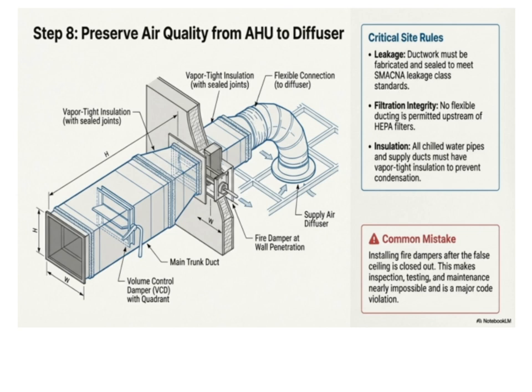They must always be accessible for inspection and maintenance, so in case of a fire, they can be quickly operated to contain the spread of smoke and flames. Finally, vapor leaks are a serious concern because they can cause condensation within the ducts. This not only damages the system, but also promotes mold growth and increases infection risks, undermining the integrity of the entire environment. By paying close attention to these details, duct sealing, proper filtering, insulation, and fire safety, we ensure our systems are safe, efficient, and compliant with the highest standards.